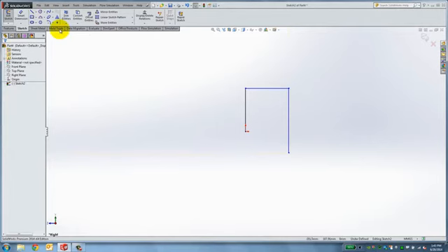It is very important that you fully define a sketch, which means that every entity in the sketch has a specific location and doesn't move. Everything that is underdefined is shown in blue and the sketch has a minus sign. You can restrict motion by using Relations and Dimensions.